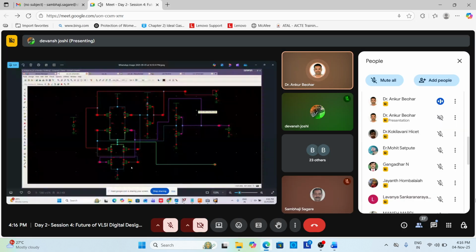Once we go for the Verilog, after this we can go for functional verification, synthesis, and then the Verilog RTL that we already discussed. RTL design is followed by functional verification, then synthesis in the form of a netlist, followed by DFT insertion and floor planning. Floor planning is followed by placement, clock tree, routing, and GDS2.